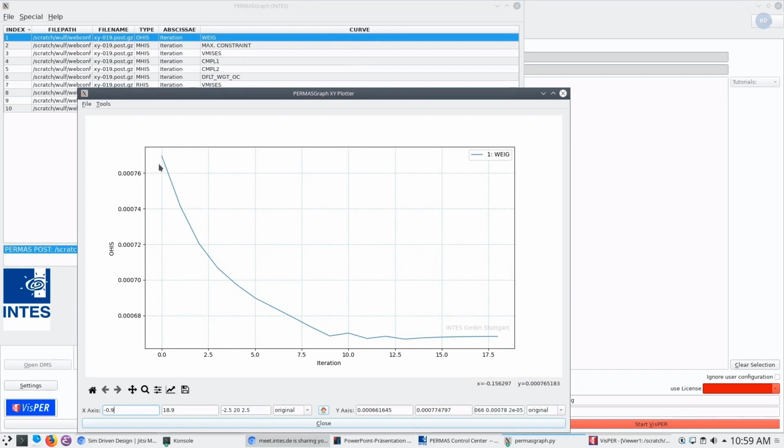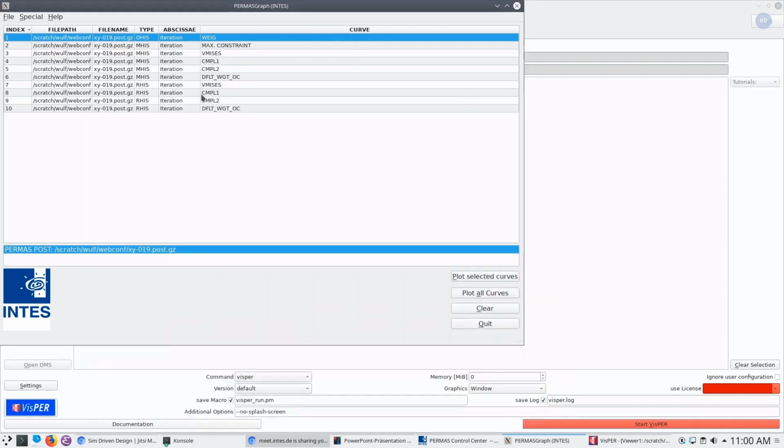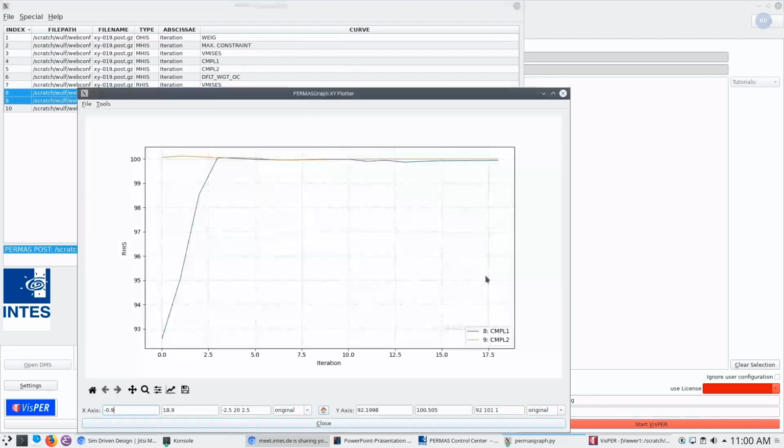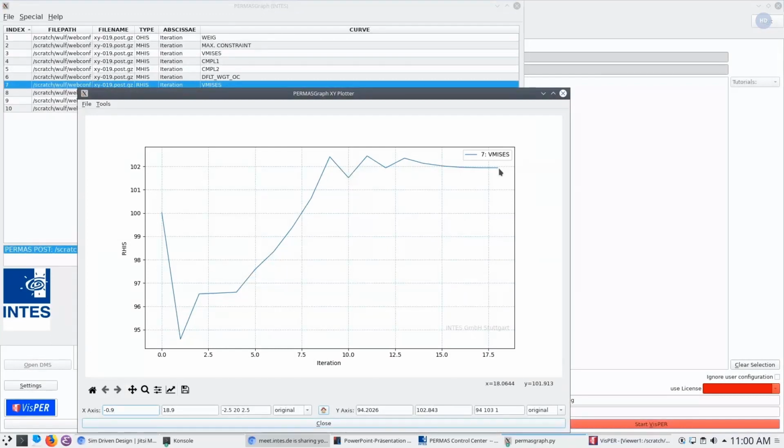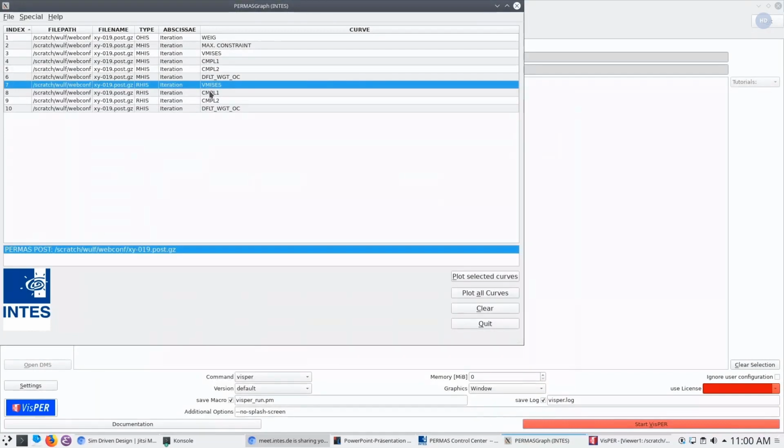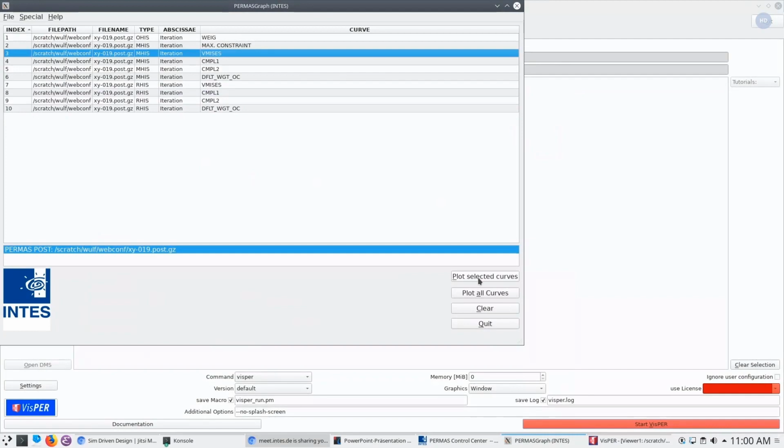It comes with a slight increase of 10% of the weight, and this is again now reduced by the shape optimization, and now is even less, maybe about 10 grams less than the result of the topology optimization. And again, I look at the compliance, the stiffness of the structure. Okay, this is exactly at the 100%. So it reaches exactly the upper limit. And I have a look at the stresses with a slight violation here, slightly above the 30 MPa, but within the allowed tolerance. Here you see the absolute value.